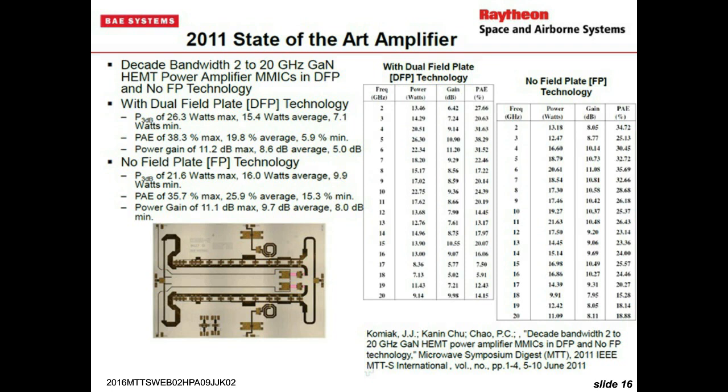By clumping devices, you lower the impedances, and so it's non-uniform in periphery. You can also see on the output drain line that it's non-uniform in characteristic impedance in the output network, and there's no termination on the gate line. All techniques to do a non-uniform distributed power amplifier.